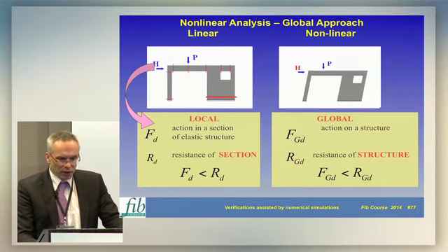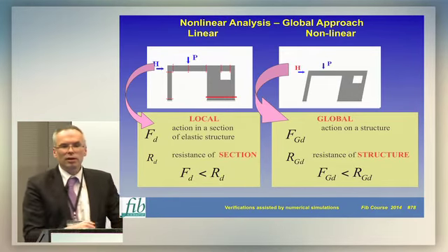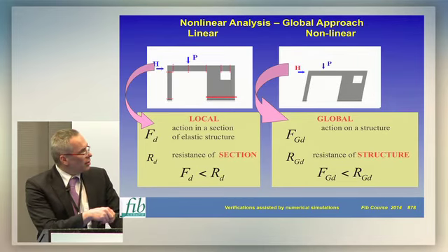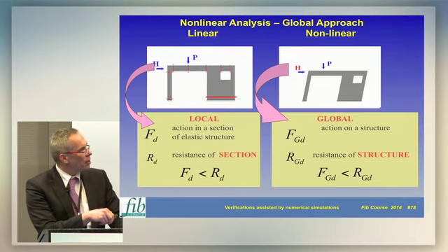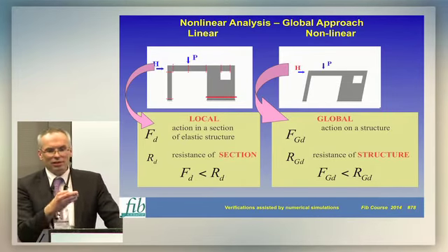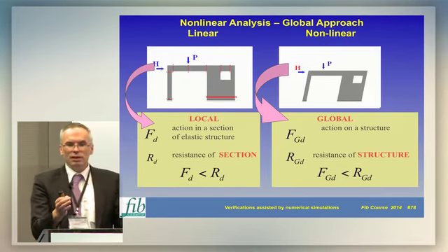Now such an approach is not very suitable for nonlinear analysis. For nonlinear analysis, it is better to apply the loads on the structure, keep increasing them until the failure, and then we calculate the resistance, not of the section, but the resistance of the structure with respect to the given set of loads.